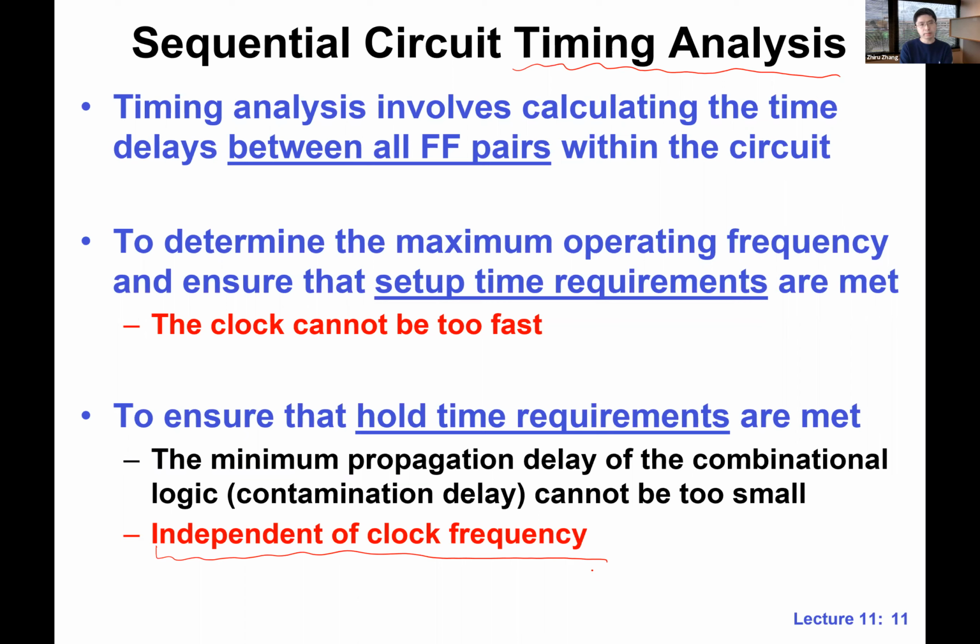Although it's kind of counterintuitive, since hold time happens after the clock edge, the cycle time does not matter much. Hopefully it's somewhat clear to you. These are still abstract things, and I'll make it much more concrete, but these are the three things. We need to look at all the pairs, although in many cases we will just look at a single pair, and we need to care for the setup time and the hold time.